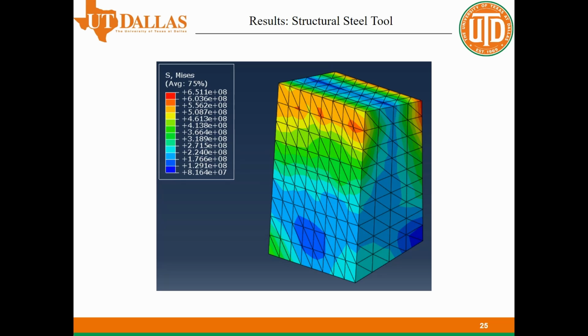While the stresses in the aluminum did vary slightly, only by a couple of percentage points, we know it will deform the aluminum. We're just concerned with the stresses in our tool. As our tools are fixed at the top, there's an obvious stress concentration there. However, in actual use, the tool is held by a tool holder. It would not have this same concentration. Therefore, we're only focusing on the stresses near the cutting edge of the tool.